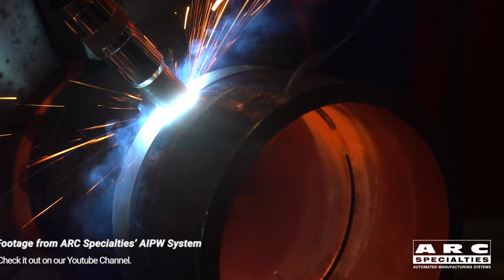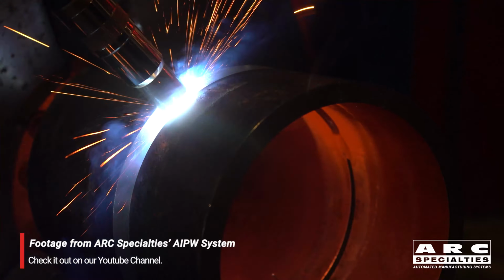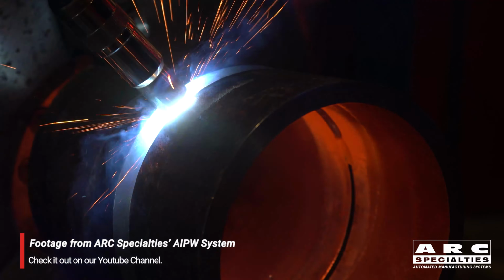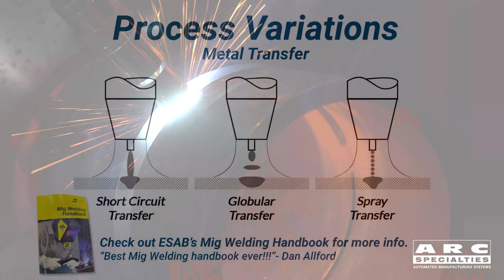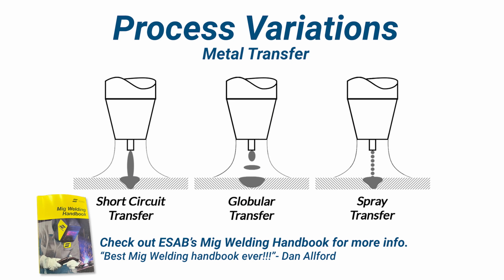This week we're talking about gas metal arc welding, which is also called MIG for metal inert gas, and it's also called short arc. But that's not entirely true because short arc is really only one of three transfer modes used in gas metal arc welding.